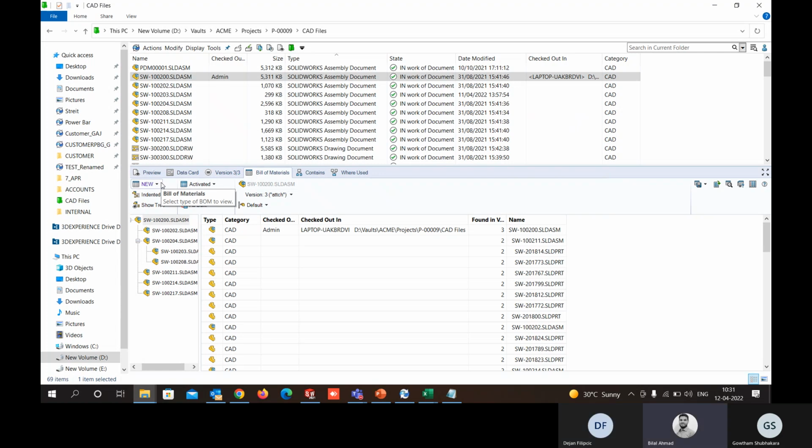So how we used to do it for all the standard components was we were not using them directly from SolidWorks library, but rather if there was a mechanical component, it will have an article number. That article number is defined in the properties. That number is coming from an ERP or another system, and then you use only the components which are in your own library. You don't use them directly from SolidWorks. If you want to use it directly from SolidWorks, then you have to assign an article number to it, and then you can have it.